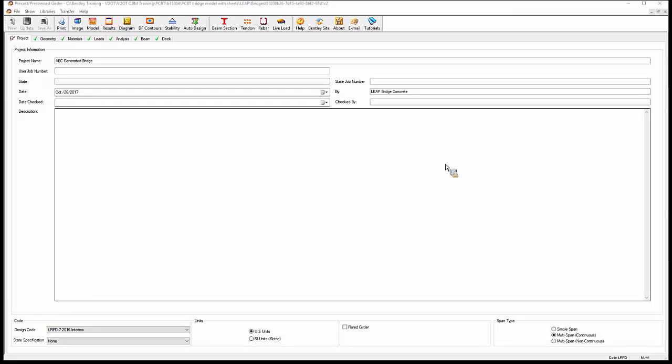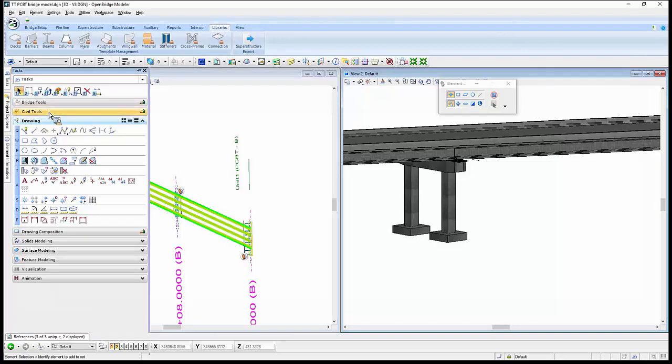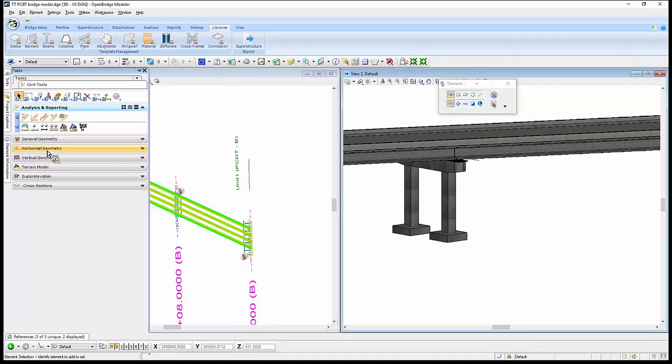Just to add, it doesn't need MicroStation to run because it runs on the Power platform. So you install the software, and it has MicroStation plus a fair amount of the roadway design software, because, like I said, we have all the horizontal alignment, vertical geometry, terrain modeling, and superelevation tools. I think so far what you cannot do is corridor modeling, but it has everything else. We have a lot of the basics here.